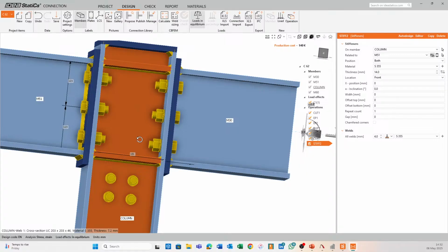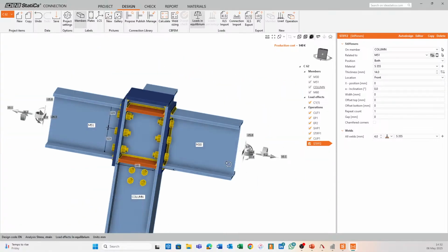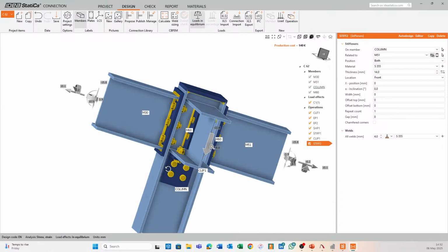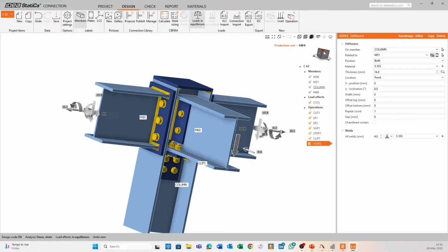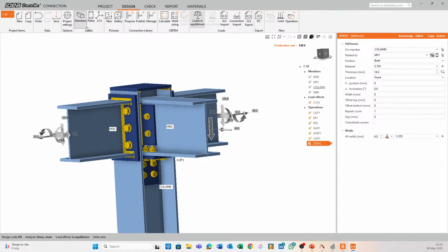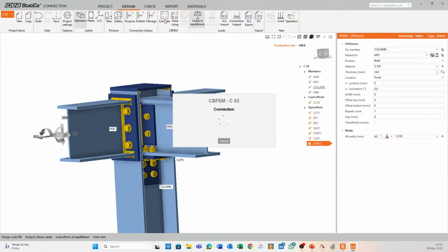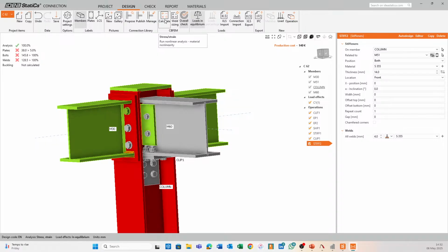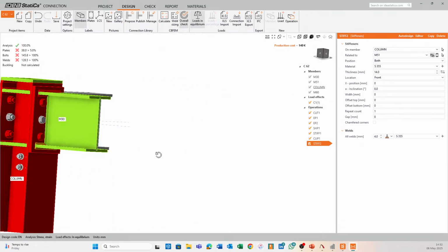Okay, let's see if that improves it significantly. So we'll do this once more. I think we're not going to win that much more out of modifying this connection to the nth degree. At some point, we also have to realize that, okay, cool, now we really do have to upsize our member. Wow, look at that, down to 38%. That was quite significant, actually.